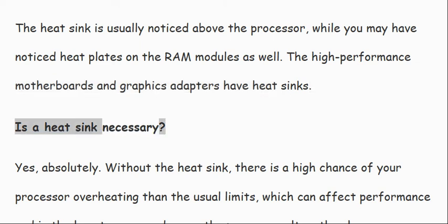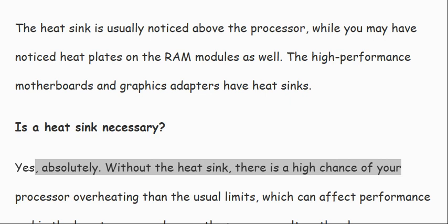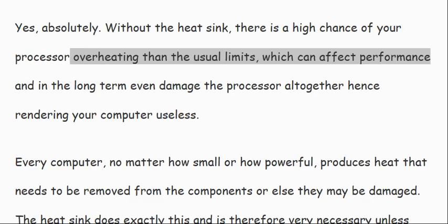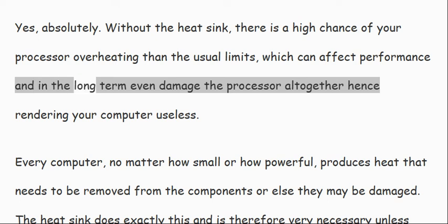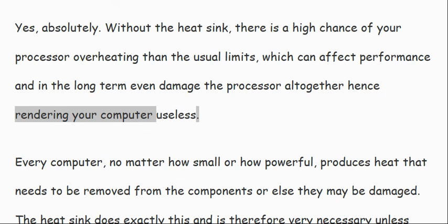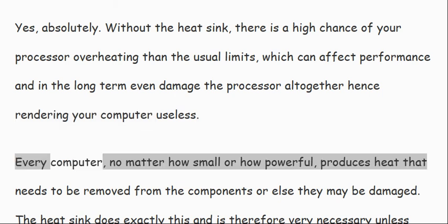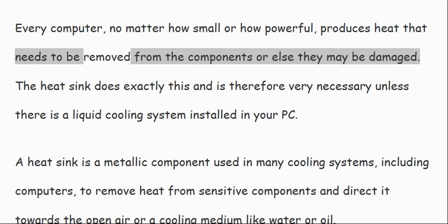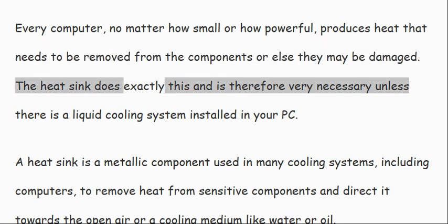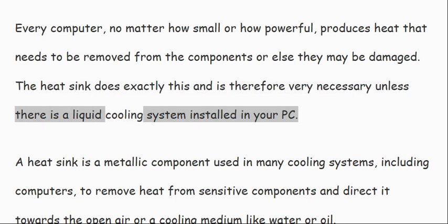Is a heat sink necessary? Yes, absolutely. Without the heat sink, there is a high chance of your processor overheating than the usual limits, which can affect performance and in the long term even damage the processor altogether, hence rendering your computer useless. Every computer, no matter how small or how powerful, produces heat that needs to be removed from the components or else they may be damaged. The heat sink does exactly this and is therefore very necessary unless there is a liquid cooling system installed in your PC.